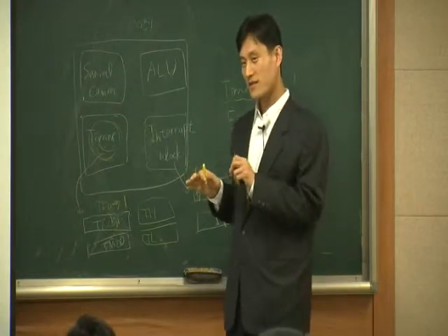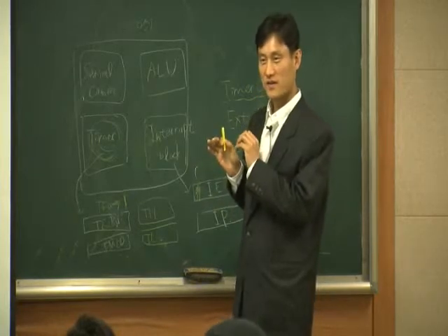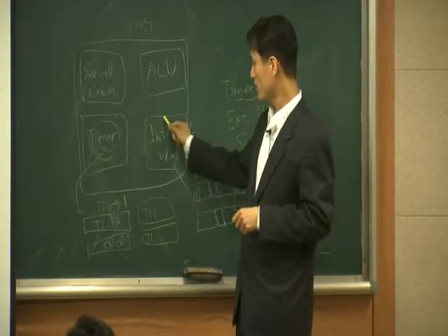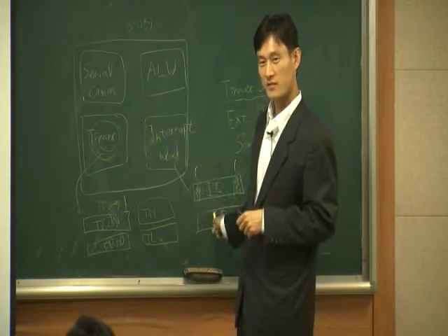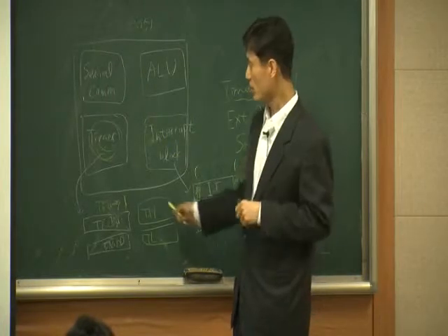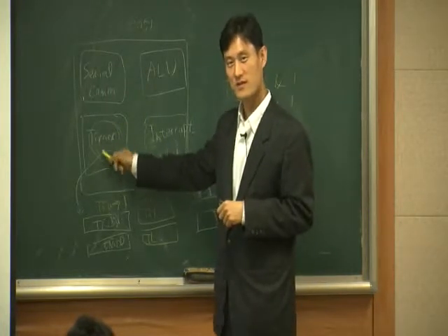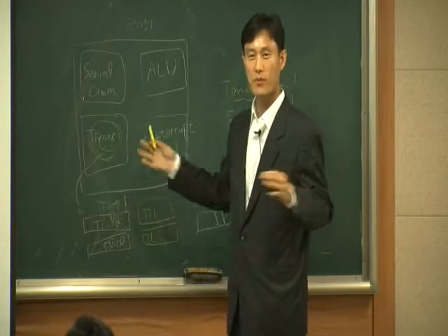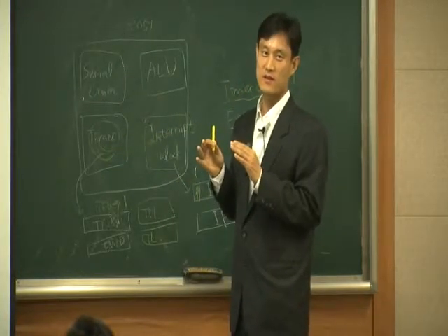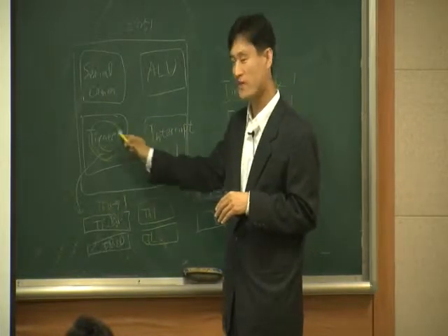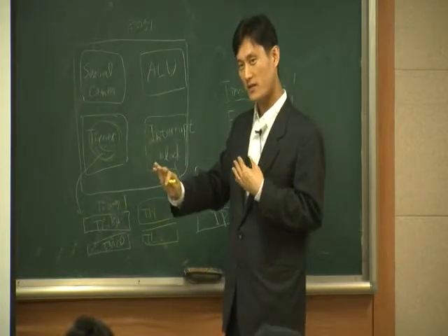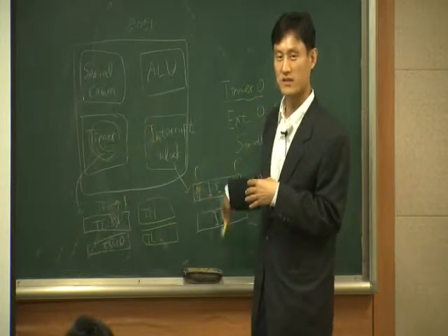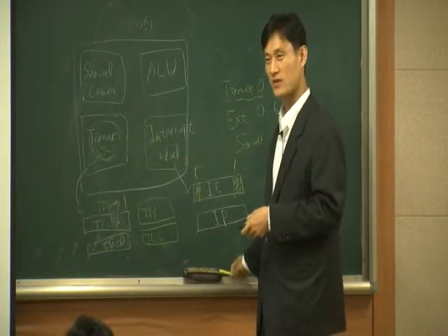So we are talking about two different hardware blocks. Two weeks ago we talked about this hardware, the interrupt block. Last week we talked about this hardware. But actually you need to program both all together. Okay? We learned the two different blocks separately, but you need to program them all together. Only then do you get an interrupt.